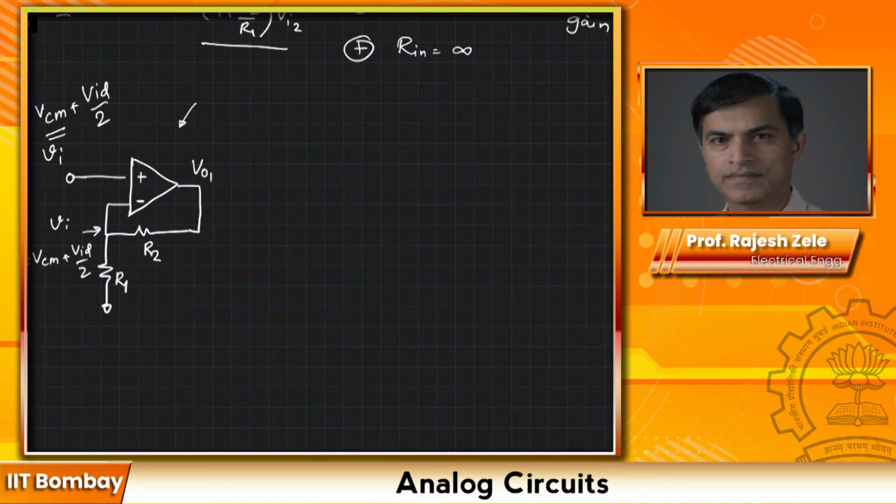Okay. So what this means is, for example, let's say the common mode signal is 100 millivolts and the differential signal is 1 millivolt for that matter. This 100 millivolts may be coming from the body hum, the 50 hertz hum that you're riding, and then 1 millivolt is what actually you're trying to detect.